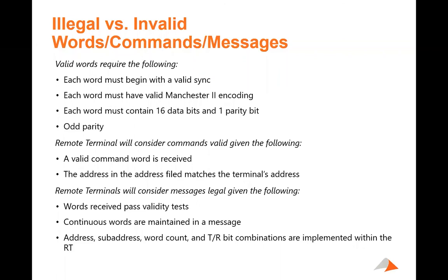Each word must have valid Manchester II encoding, so if there's a violation in the bit as it's crossing, then that would be invalid. Each word must contain 16 bits and 1 parity, and the parity must be odd. If there are any violations here, it's invalid, and basically nobody on the bus should respond to that. It should be a total no response, just received like there's nothing there at all.